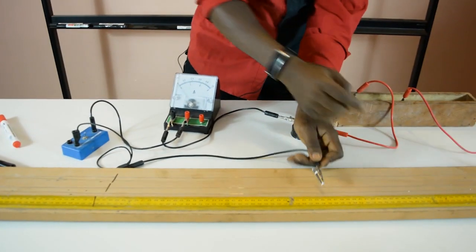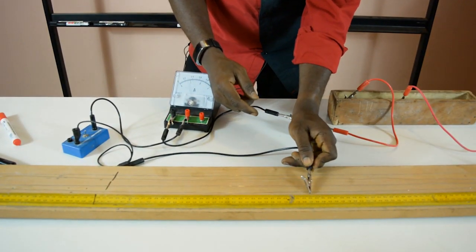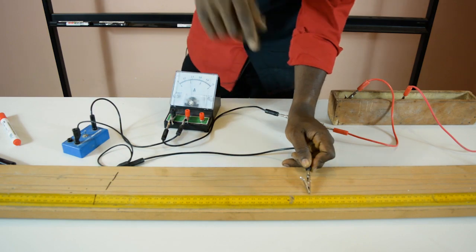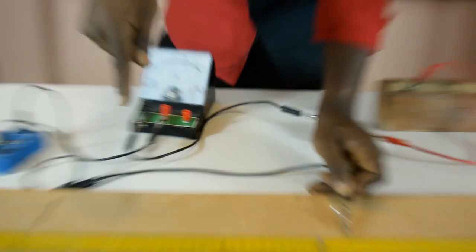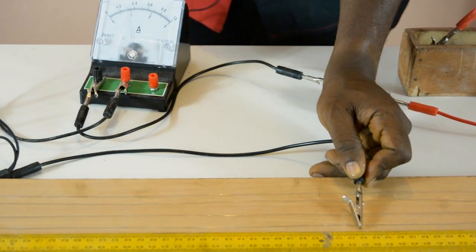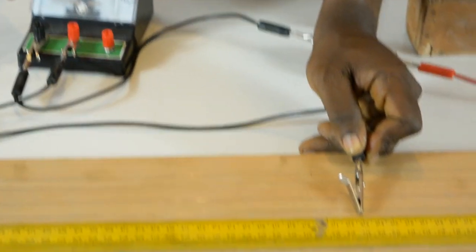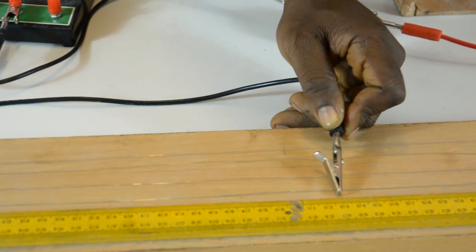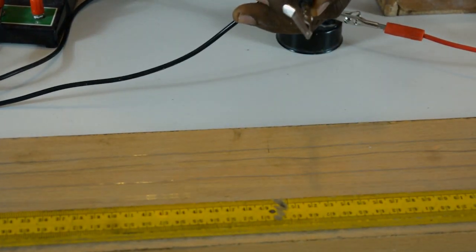These ones are just reserved. So I put it right on it there. You don't scrape it, you tap it. When you scrape it, you increase the resistance of that wire. And when you increase the resistance of the wire, then you are going to affect the reading, the outcome of the experiment. So now this is just to tell me that my circuit is complete.